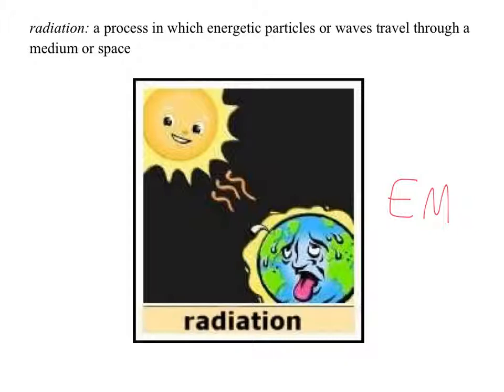That oxygen that continues to flow afterward, though, involves convection. And then conduction occurs if you were to heat something up. Say you put a big pan on top of it, or a pot where you have water in it. You want to heat up that water. Well, conduction is occurring there because the heat from the flame hits the actual metal. Conduction is what heats the water, and then the water heats itself up via convection. So a lot of the time things are being heated, it's all three of these processes occurring at once. Okay? They're all related to one another.